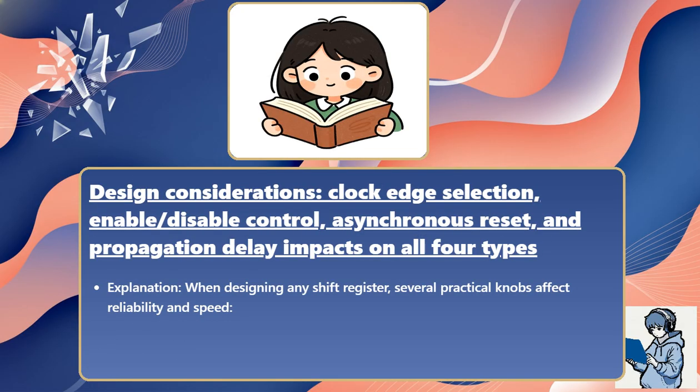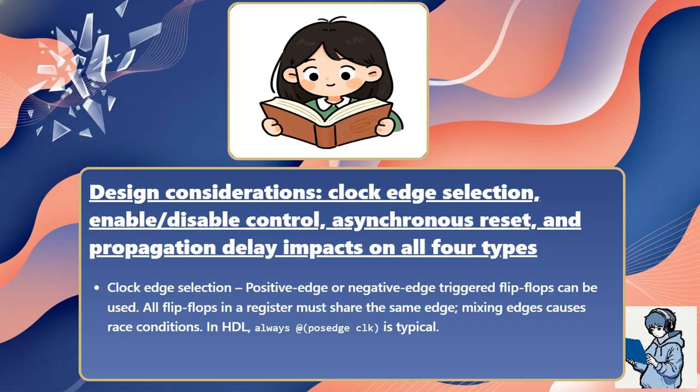Explanation: when designing any shift register, several practical knobs affect reliability and speed. Clock edge selection: positive edge or negative edge triggered flip-flops can be used. All flip-flops in a register must share the same edge. Mixing edges causes race conditions. In HDL, always @(posedge clk) is typical.